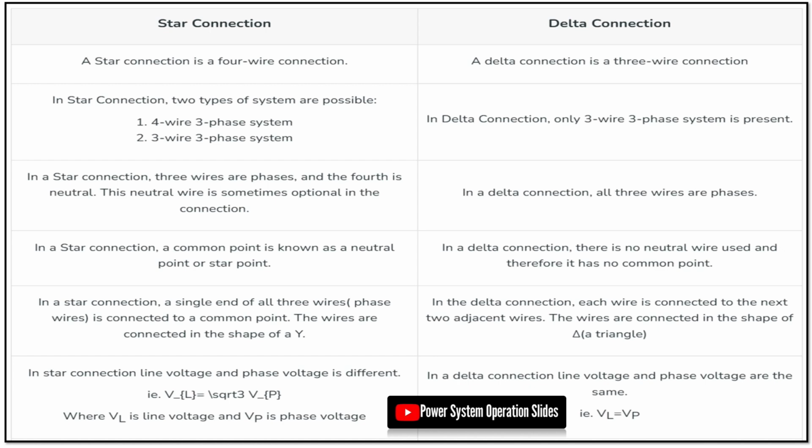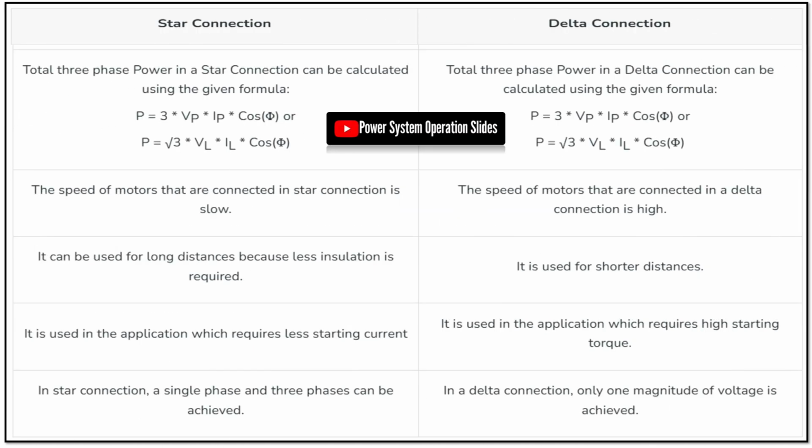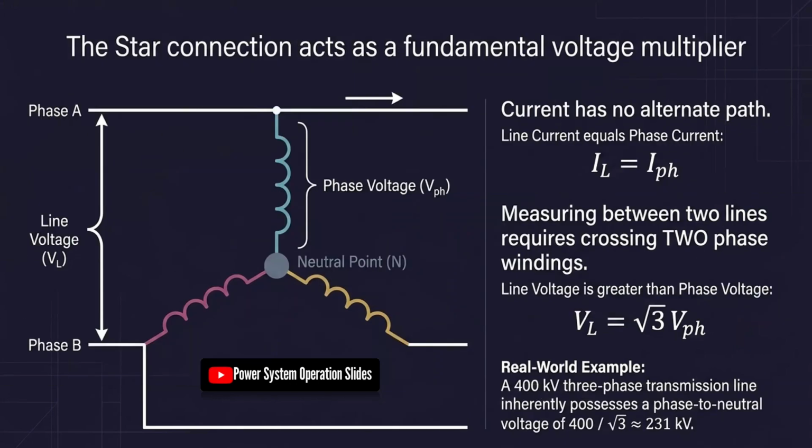In a perfectly balanced three-phase system, the three-phase currents cancel each other at the neutral point because they are separated by 120 degrees. Consequently, the neutral current is theoretically zero under perfectly balanced conditions. In practical electrical systems, however, loads are rarely completely balanced. Commercial and industrial facilities contain different combinations of lighting, heating, air conditioning, motors, electronic equipment, and other loads that change continuously. Therefore, the neutral conductor can carry significant current during normal operation.